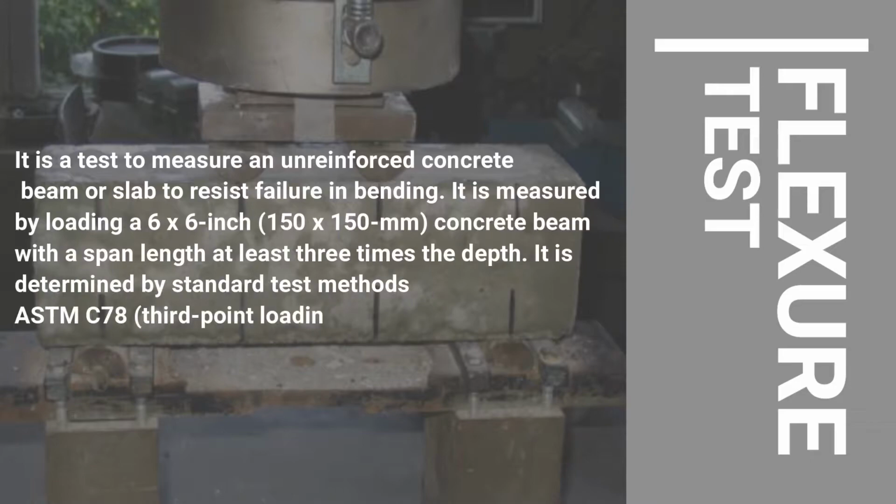The second method is the flexure test. It is a test to determine the ability of an unreinforced concrete beam or slab to resist failure in bending. It is measured by loading a 6 by 6 inch or 150 by 150 mm concrete beam with a span length of at least 3 times the depth. It is determined by standard test methods ASTM C78 or third point loading, or ASTM C293 or center point loading.